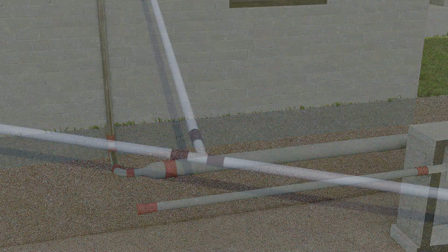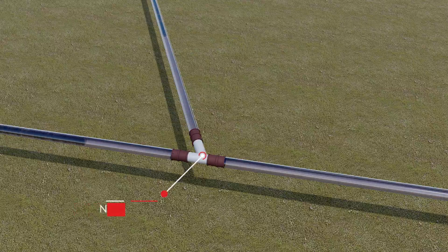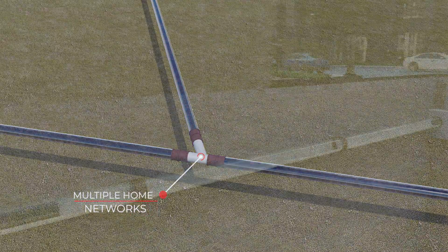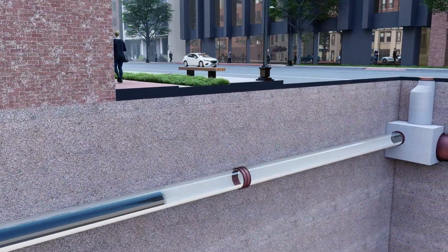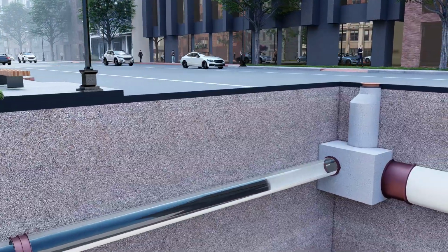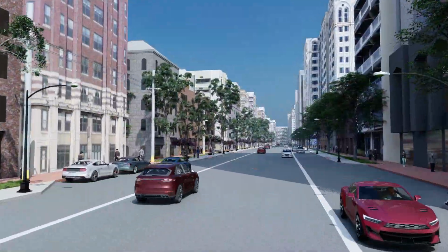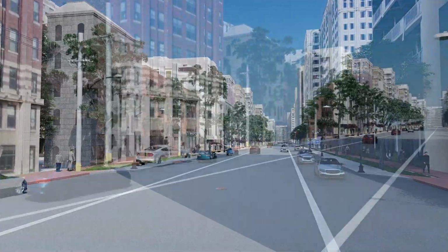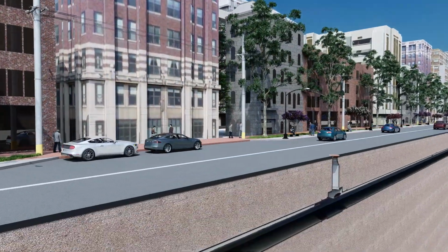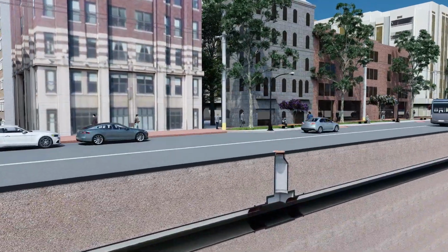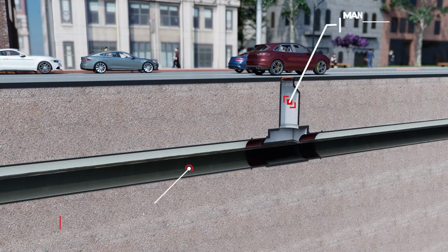A network of pipes will be made to connect the houses to the sewage network. Pipelines will be placed underneath the roads, which will connect them to the bigger pipes, the trunk sewers. For maintenance, several manholes will be included at regular intervals.